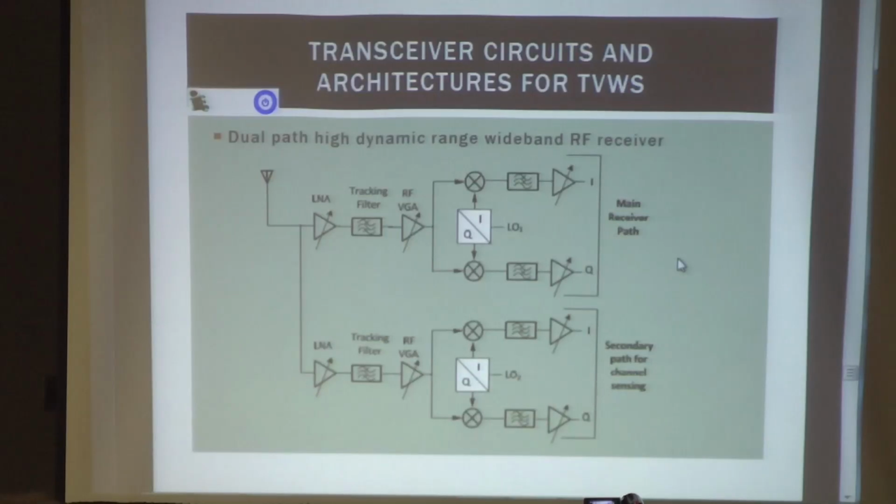And the important point over here is that the LOs here are different. If you make them different, then you can support something like frequency hopping, for example, or non-blocking sensing techniques.